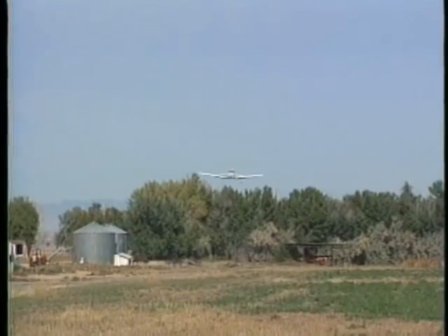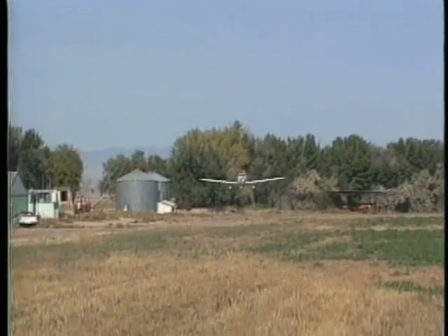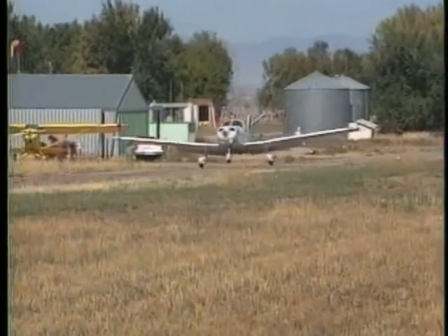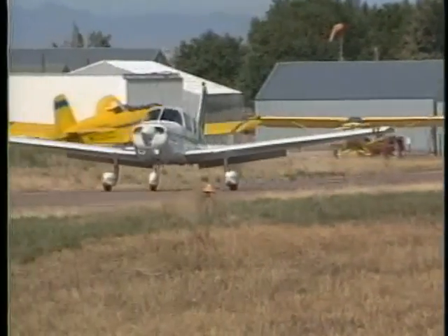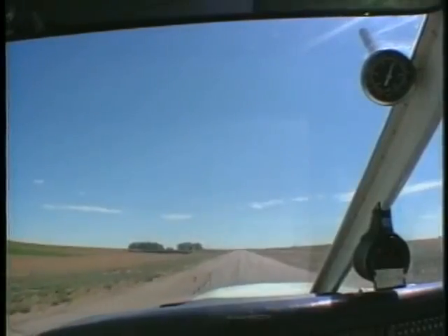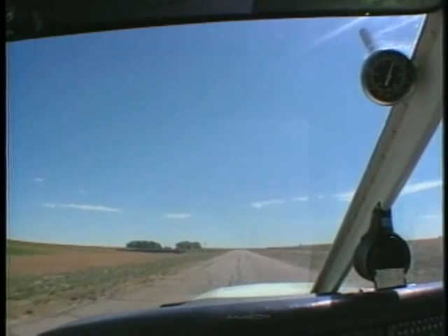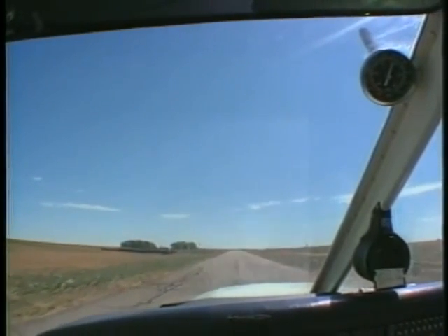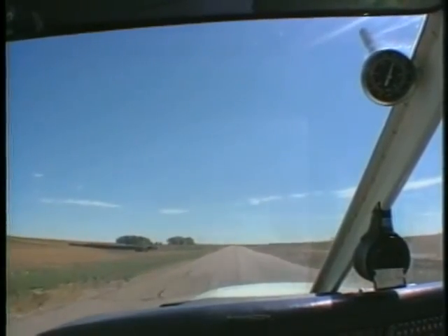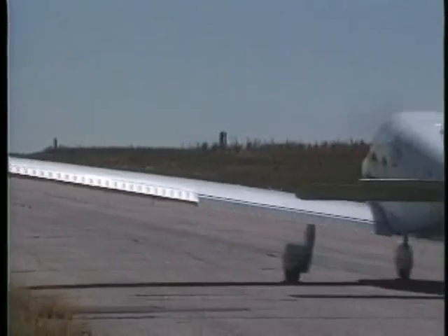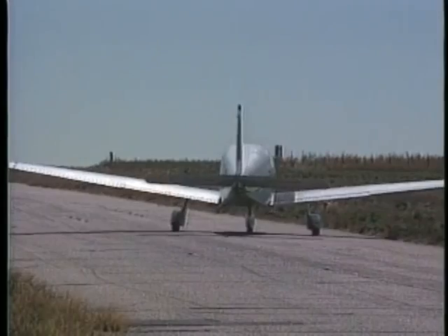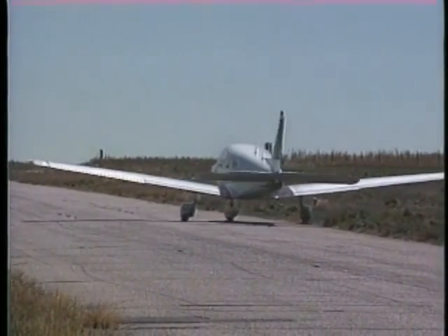If you maintain the recommended airspeed, you'll touch down near the designated point on the runway with very little floating. After touchdown, lower the nose as soon as practical and apply maximum braking procedures. This usually includes holding back pressure on the control wheel to transfer more of the aircraft's weight to the main gear. Maintain positive directional control and follow the recommendation in the POH for flap retraction. If you touch down at the correct speed and smoothly apply maximum braking, the landing roll will be extremely short.